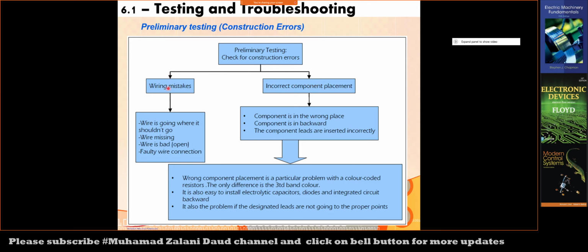In terms of wiring, for example, we will check whether a wire is going where it shouldn't go. For example, sometimes we mistakenly connect a wire from the active terminal, the voltage terminal or live terminal, to the ground. So some inspection in terms of missing wires, and then wires that are bent or open, which are not completely joined or connected, and then faulty wire connections, right?